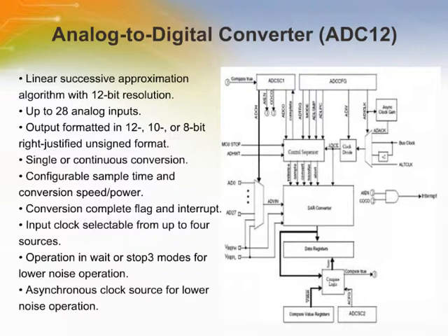The ADC can perform an analog to digital conversion on any of the software selectable channels in 12-bit and 10-bit mode. The selected channel voltage is converted by a successive approximation algorithm into a 12-bit digital result. In 8-bit mode, the selected channel voltage is converted by a successive approximation algorithm into a 9-bit digital result.